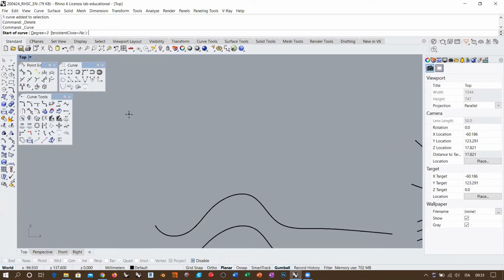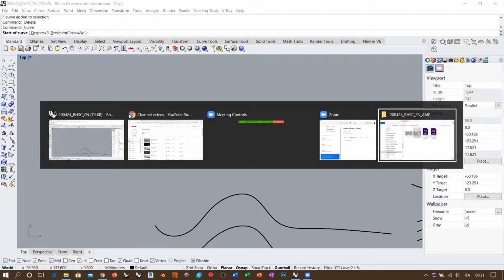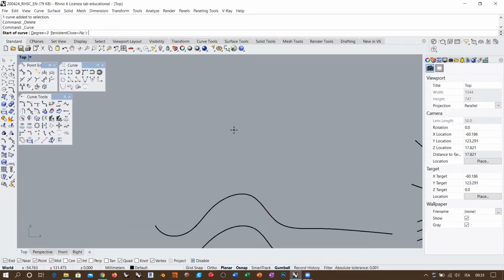Let's consider the front part of the handle. We need four areas where the handle is capable of hosting our four fingers. So I'm going to begin this line at the higher level of the surface, which is basically represented by the endpoint and the horizontal tangent direction. Then I need to go down here, and in order to go down, I will need only one, two, and eventually three control points.